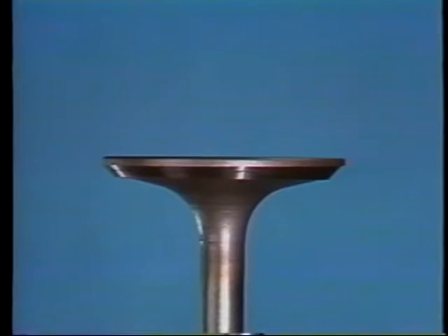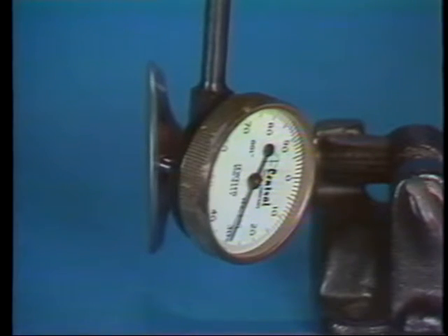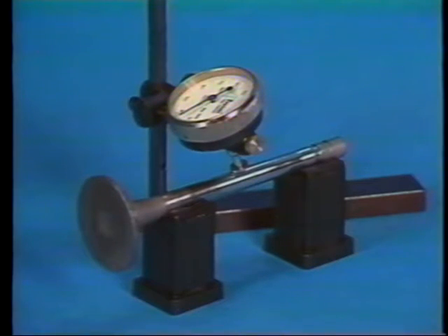The rest of the responses listed in the question are measurements having to do with valves which you should be aware of. Valve face angle, as mentioned in response B, is determined when the valve is cut or ground. Valve face runout, as mentioned in response C, is measured with a special fixture. Runout is measured by rotating the valve in the fixture and watching the indicator. Special fixtures are also available for measuring valve stem straightness.